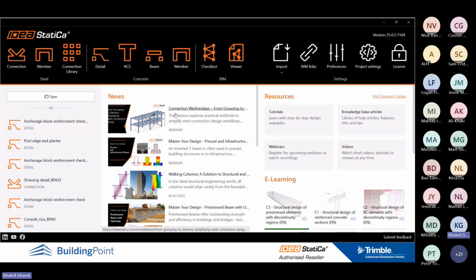So here we have the geometry, already brought into Detail 2D. And then from here, as you can see, you have different types of support. And if you have any load transfer devices, you can also use this one. Let's here use the linear support as well. By default, it goes to edge 1, but you can simply adjust it. So here we have the compression-only spring, which we mainly use for base plate design once the concrete block is interacting with the soil. But you can just adjust the boundary condition as you wish. So here I just did it.